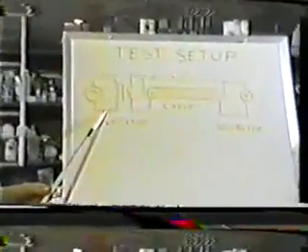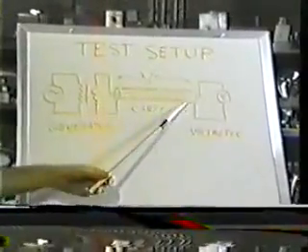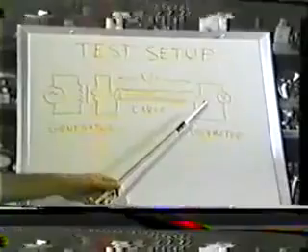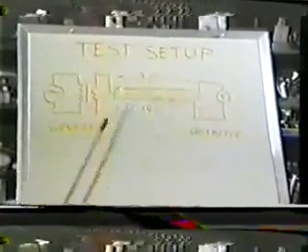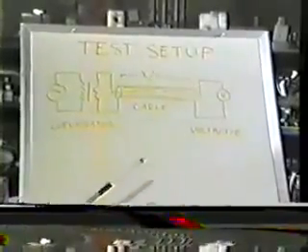In our study of electric waves, we're going to start with the well-understood transverse electromagnetic wave, and we're going to do some measurements here to determine the characteristics of such waves. To start with, we'll have a radio frequency generator and a step-down transformer to drive a long section of coaxial cable, and then a high-impedance bridging voltmeter to measure the rise of electric potential due to resonance at the distant end of the cable. Now we'll go over to our test setup here on the bench.